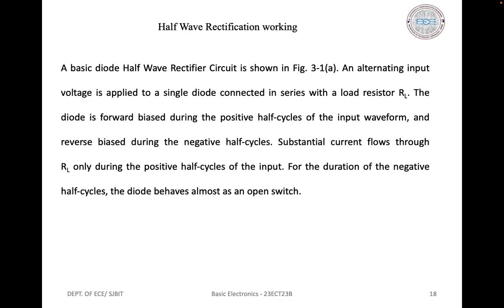Clamping circuits change the DC level of a waveform without affecting the wave shape. DC voltage multipliers are applied to change the level of a DC voltage source to a desired higher level. Logic circuits produce a high or low output voltage depending on the voltage levels at several input terminals.